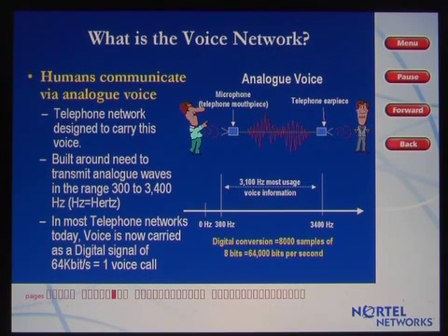For the last 30 years, most telecommunications service companies have been upgrading their networks with digital switching and transmission. In these systems, voice is now transformed into a digital signal via a device called a codec. The word codec comes from the words coder and decoder. The encoding technique generally used is called pulse code modulation, or PCM.